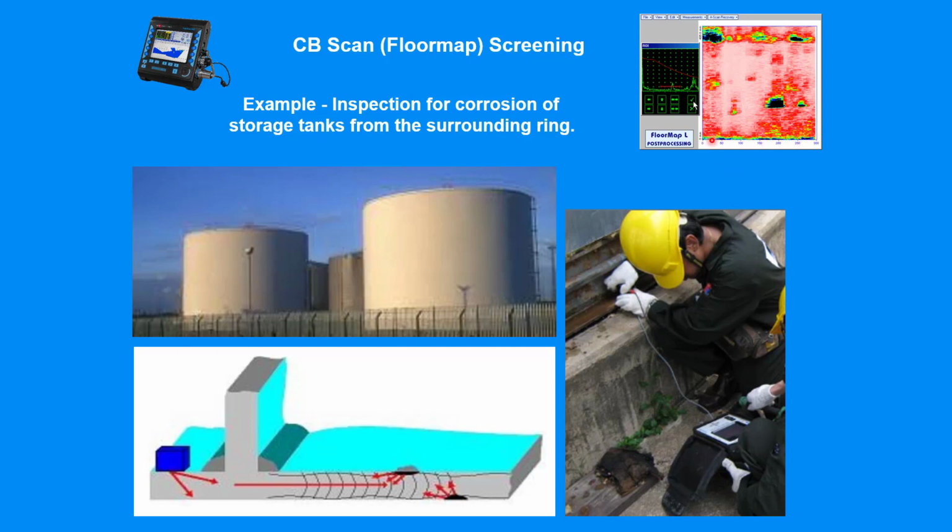Here's the initial pulse, and then in this direction you get some reflections. For example, if this is a higher corrosion, you get in this case a deeper color, black color, for example. It's a matter of how you calibrate the instrument. You cannot actually evaluate precisely the depth of the corrosion. You can do some kind of screening, and you can determine whether it's 30%, let's say close to 50 or 70% corrosion depth. That's possible.